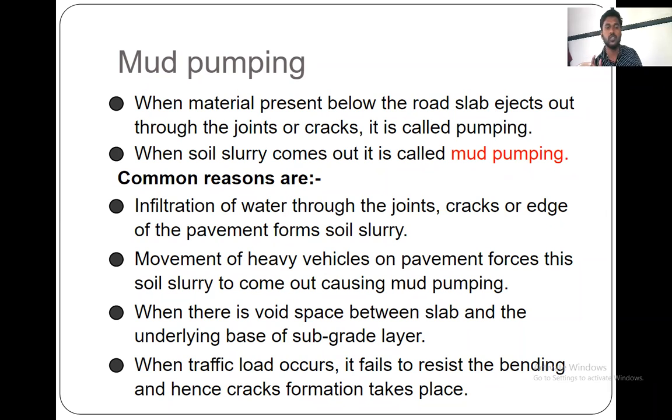The common reason is the infiltration of water through the joints, cracks, or edges of the pavement, which forms soil slurry. If water infiltrates through the joints or cracks into the base, it combines with the soil and forms slurry. Movement of heavy vehicles on the pavement forces this soil slurry to come out, causing mud pumping.